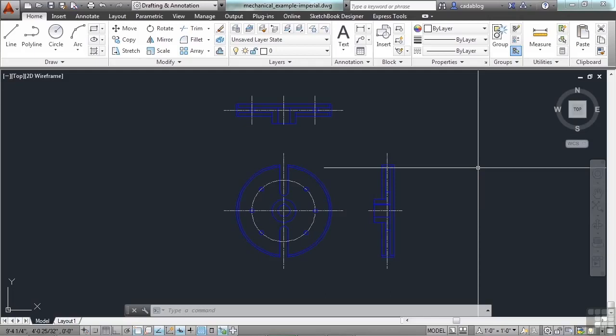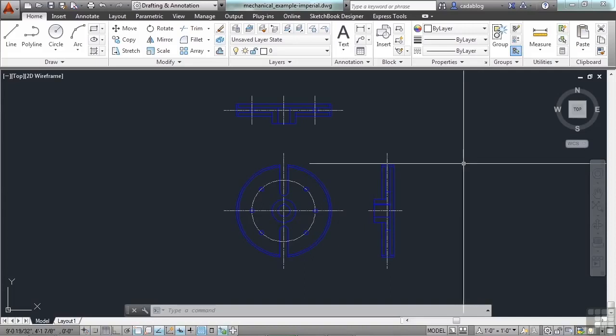It will only interpret the units when you go to print your drawing or when inserting other AutoCAD files or blocks. It will translate your drawing's units to fit the way you want to look on paper. AutoCAD will take your line work and apply it to a scale factor when it prints. It will take the size of the paper you are printing on and scale your drawing objects accordingly. When you draw, make sure to know what units you are using.